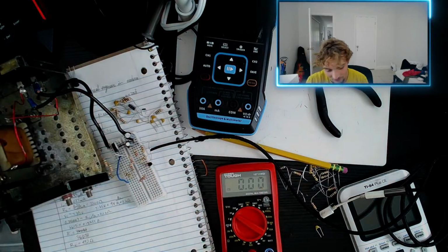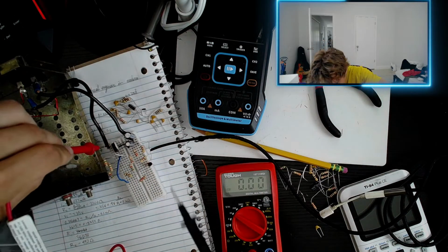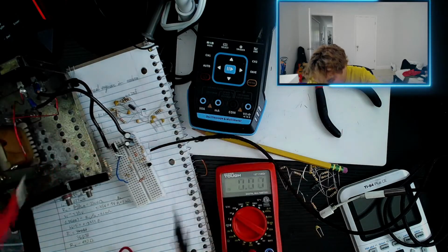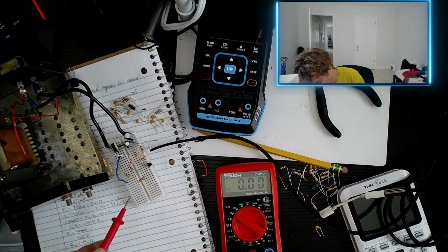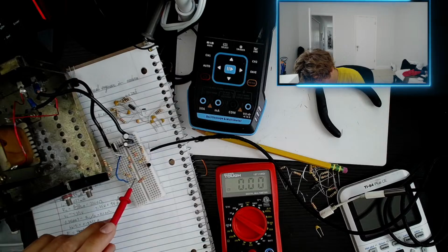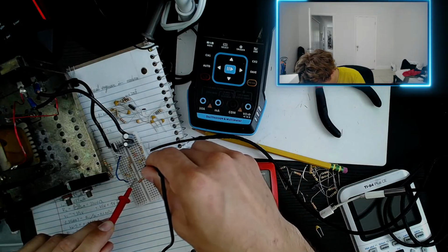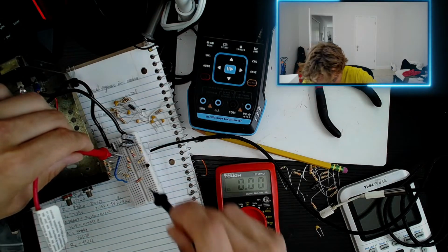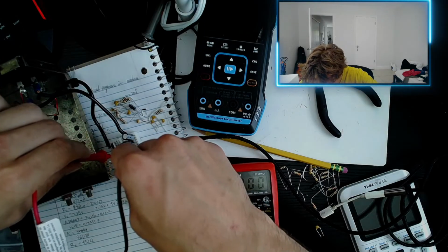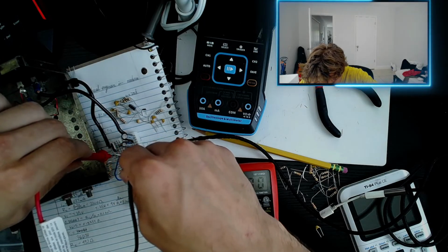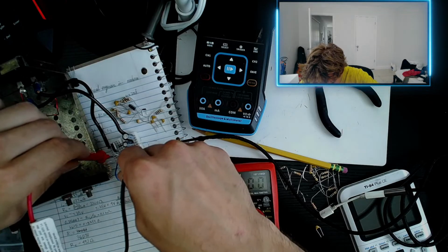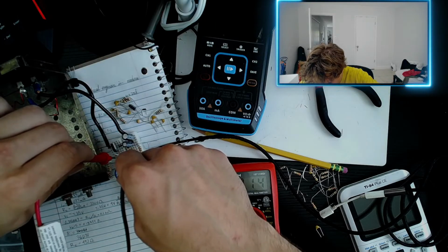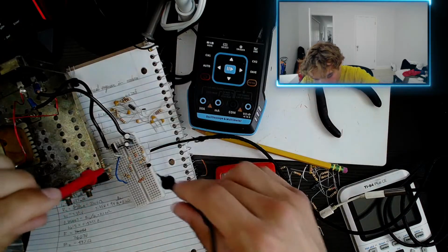Okay, we have 1.8 volts. That's not good. Let's see if we have 9 volts coming from here. We do. 9 volts there. That is our collector resistor. Oh, wait, collector should be 4.5 volts. My bad. It's only 1.8, though. That's not good. Across here should be the 7 all the way to the base. And we have 0. That's not good. Am I touching it? Oh, there. Okay, we have 8.1. That's probably acceptable.